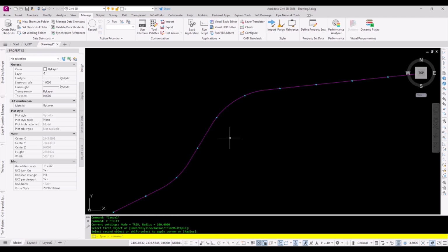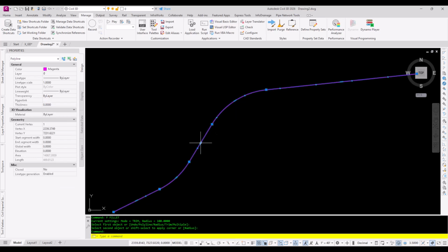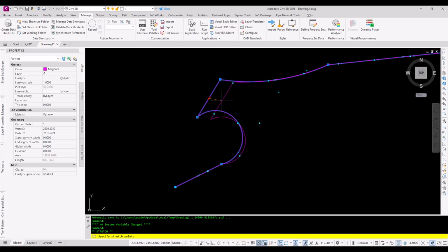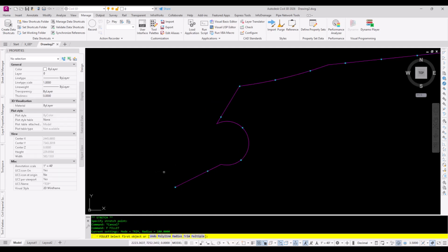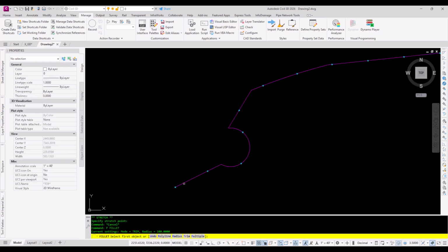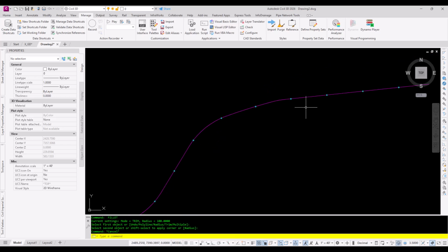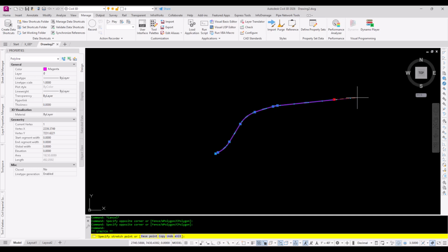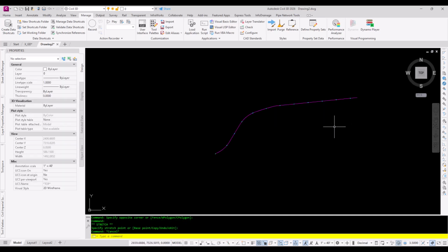So as we change our polyline, so does our array. Once we get it fixed back up, it works just fine. So I made a little extreme change here. So let's make some extreme fixes, shall we? 100 feet radius, and now everything matches along the line. Same thing if you extend it or decrease it. Same thing with the divide as well.